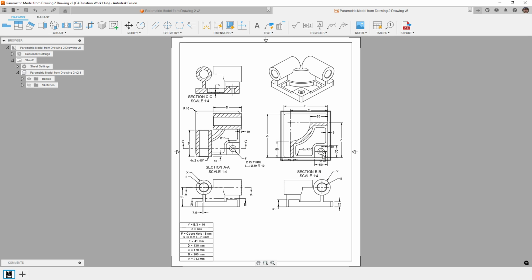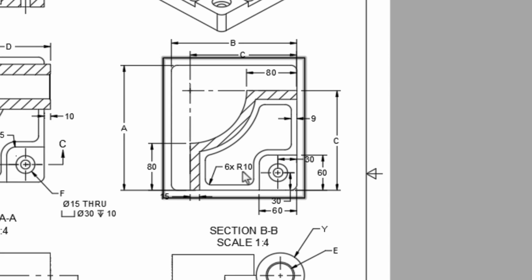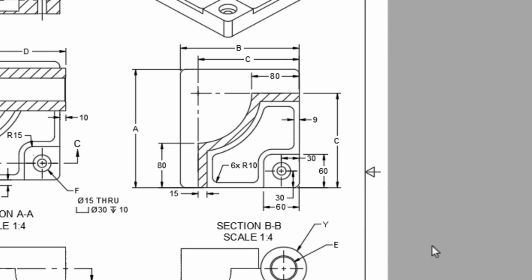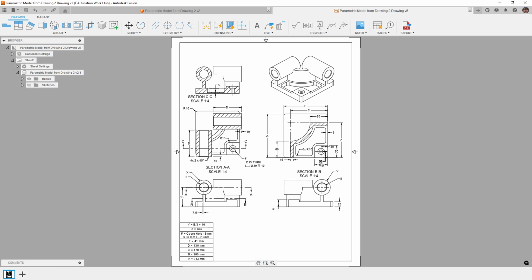Other sections, for example, this little raised section with the counterbore hole, that has to come before this recess happens because that's completely offset from the profile that's made. Now, with that, we also need to think about how to define the hole location, what's the order of operations where we're going to add things like these cylindrical bosses on the top, because the center of them would have the rib, that raised section in the center. So we need to think about how we're going to add them to the model, at what point we're going to add them, and so on.